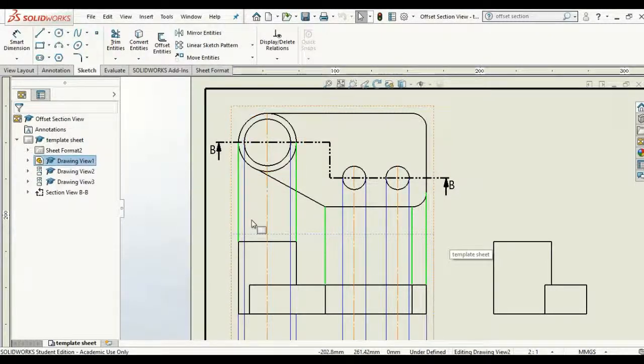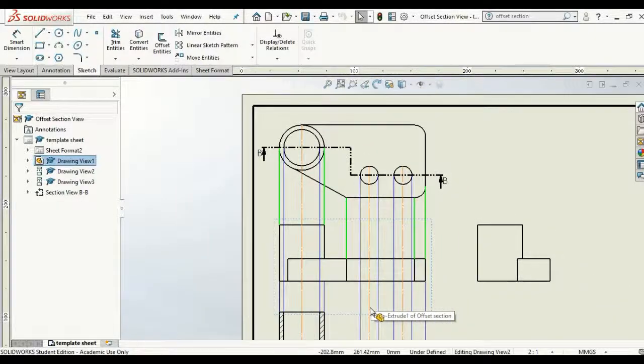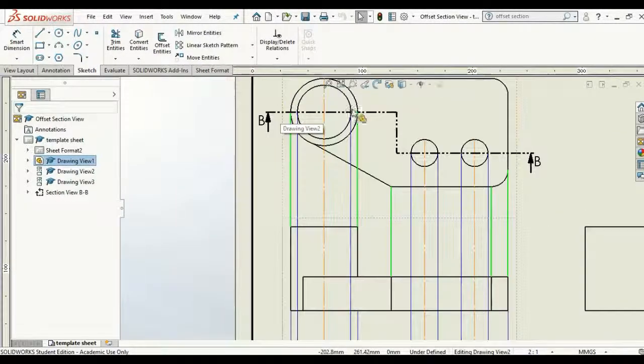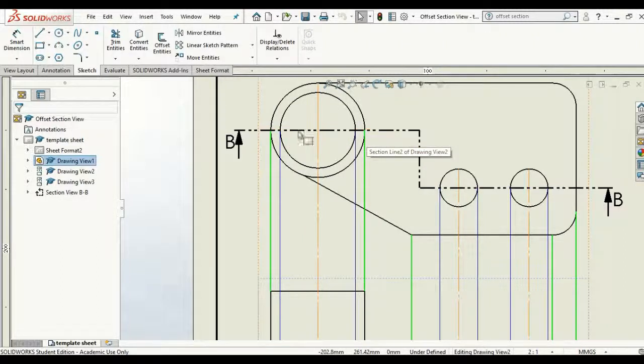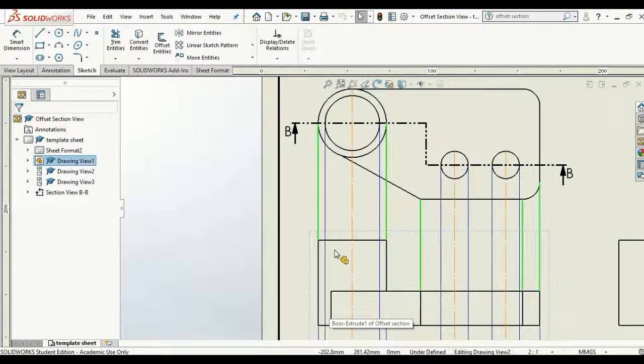So when we project down our front elevation, we can see all the features apart from the internal features. So we can't see the holes for the bolts, or we can't see the hole that houses the actual flag stick itself. And just for this instance, we're not going to have our hidden details shown. We're going to project them further down. So if we were to look at just the inside circle here, for example, for the flag stick itself, when we bring down those lines, we can see that they're going to be hidden like so. So those two blue lines are going to be hidden there.